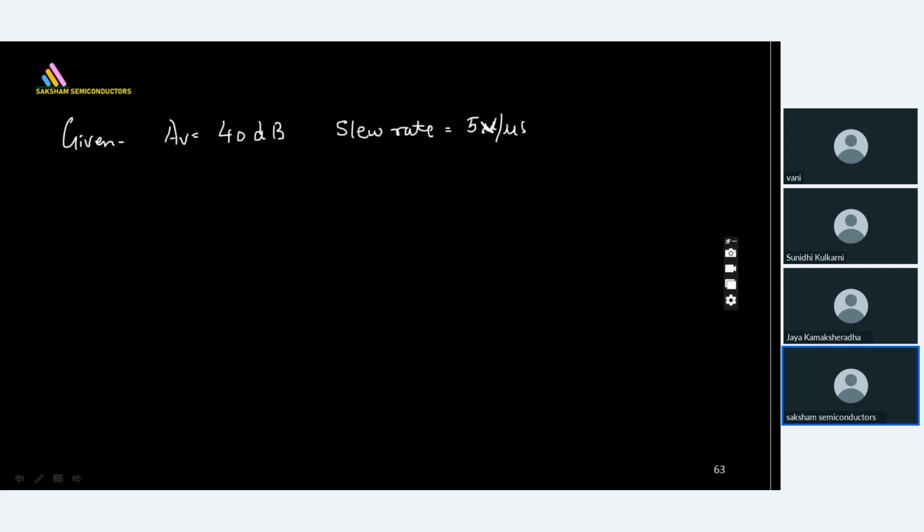And what is it going to indicate? You give the input at this particular instant, and you should see the output the very next instant. It should not happen that you give the input now and you see the output after 5 minutes. That will be a lot of delay. Those kinds of delays should always be avoided, and that's basically controlled with the help of your slew rate. That's how the slew rate is going to work.